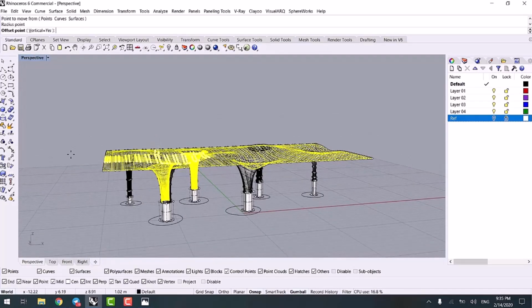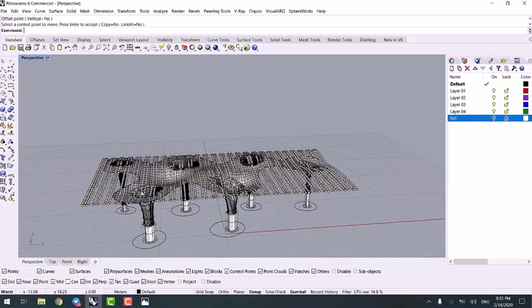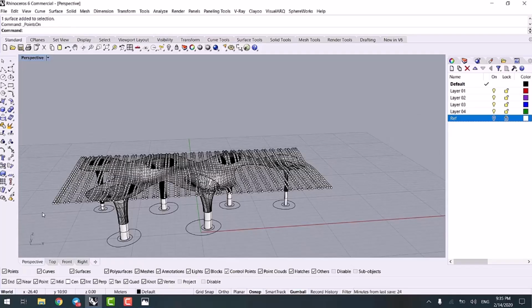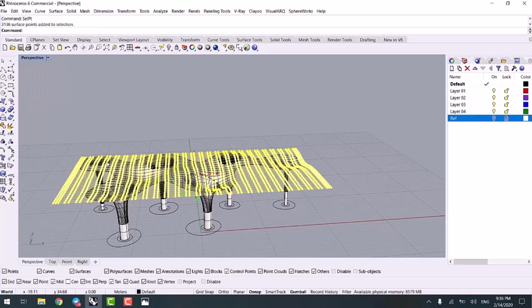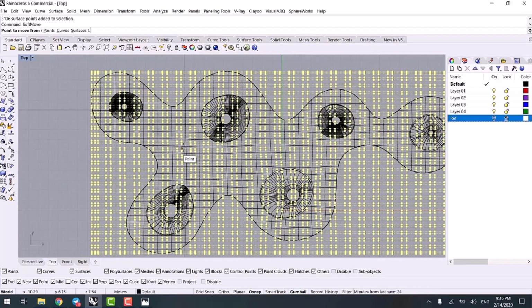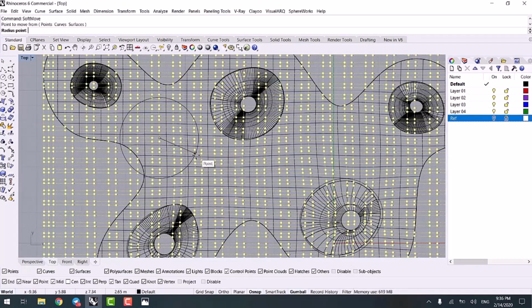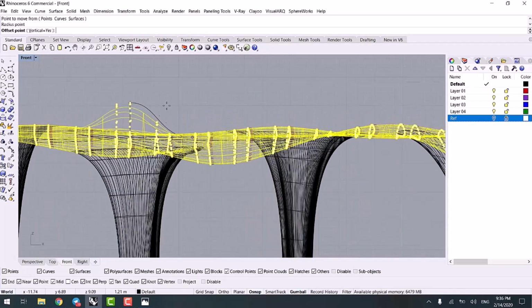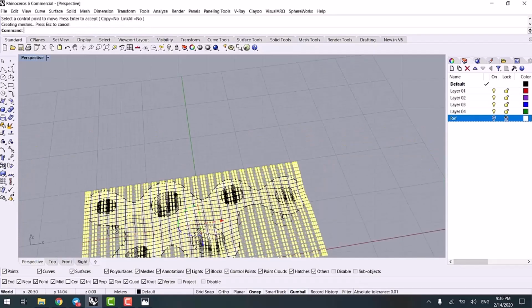So, in a nutshell, we turned on the control points, selected them, and then executed the soft move command. We could even rebuild it so we could have increased the number of control points. And we'd like to move our control points in this radius and area to this point. Now enter and finish this part.